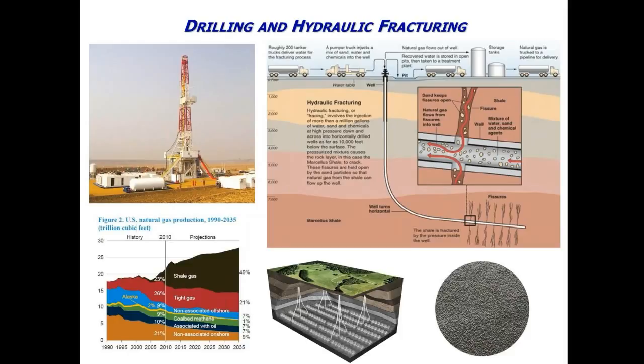What this means is that as you go to, let's say, 10,000 feet below the surface, you need to pressurize this formation, which is very low, darcies or nanodarcies in permeability, with shale formation simply by pumping highly pressurized fluids or frac fluids, which are viscosified. This results in formation of cracks or fractures or fissures that need to be kept open.